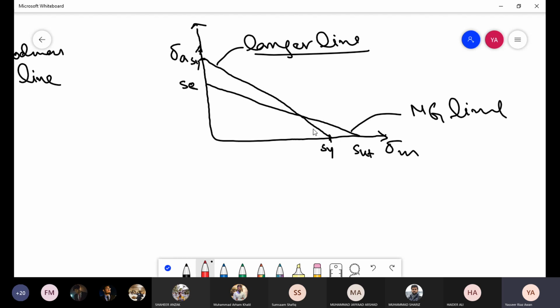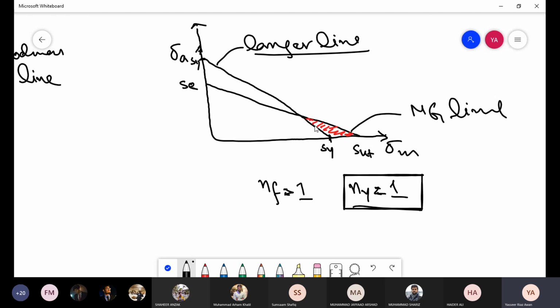So now there is a region here from the fatigue point of view. If I calculate a fatigue safety factor, that would be greater than 1 for this region, but the yield safety factor would be less than 1. So when we are designing for fatigue, we also have to check for yielding. So first we can check for yielding. That would mean either our part fails in the first cycle yield or it doesn't fail. If it doesn't fail, then we can check for fatigue.